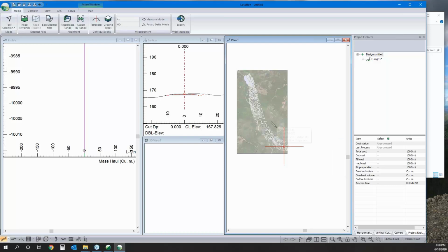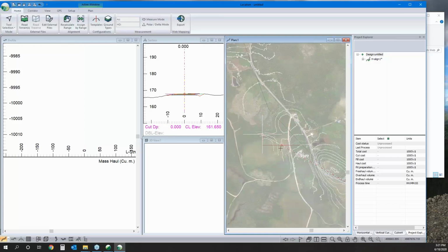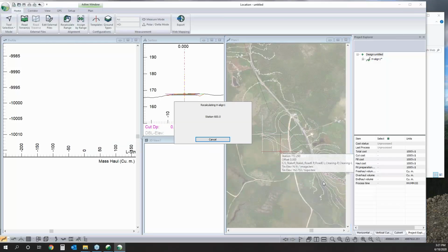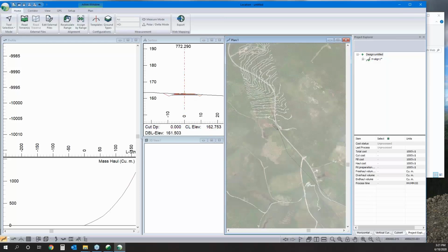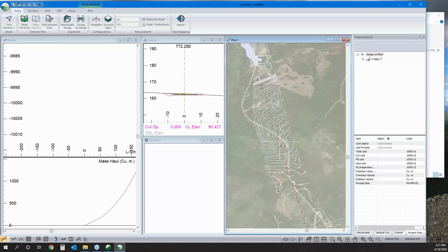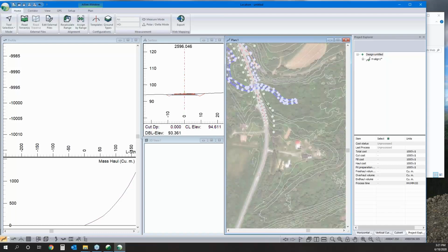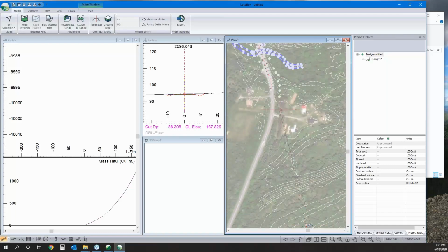So this will be a two-click process. First I'm going to choose the Add IP tool, and I'm going to say let's follow the existing tangent of that road. So this is an upgrade example. Let's come out here, keep it fairly straight. And we've got a little bit more going on in here. Let's put that curve back here.